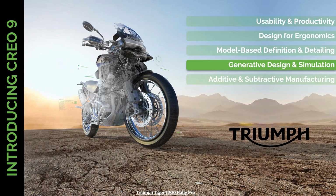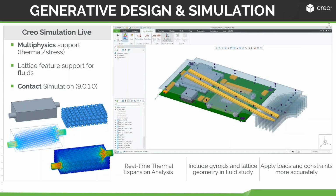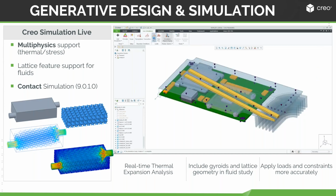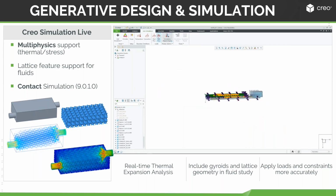Generative design simulation, as I said, is more of an extension of what's been introduced. Creo Simulation Live now has multi-physics support, so we can actually combine thermal and stress together in the same analysis. It previously had to be separate. There's also lattice feature support in fluids.